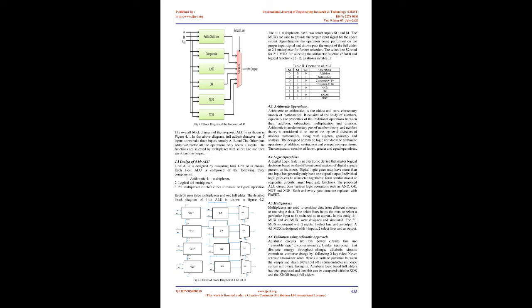Sub-threshold adiabatic logic is a new energy recovery logic. In P. Kalyani et al. [9], the efficiency of all logic gates with this novel logic is compared with the conventional counterpart. The performance of each logic gate circuit and energy consumption is studied in terms of different technologies, supply voltages, and operating frequencies. The proposed circuits are designed and simulated using Cadence technology. The simulation results show that the sub-threshold adiabatic logic saves more than 90% of power compared to static CMOS.